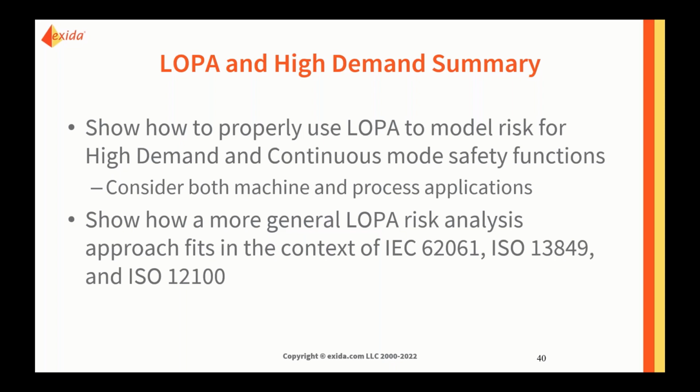If instead a risk matrix is something that you can convert into a set of frequency targets, then that can be a LOPA analysis, and a high demand safety function initiating event can be used to improve the frequency down to a level that is acceptable according to that risk matrix. But yes, some risk matrices will be inherently low demand oriented in their application.